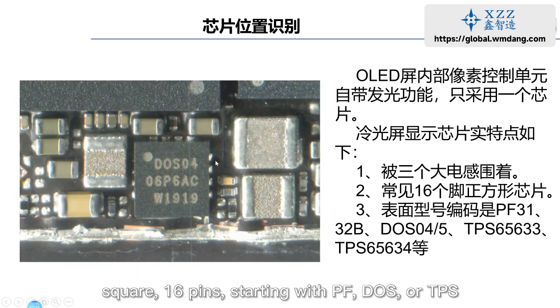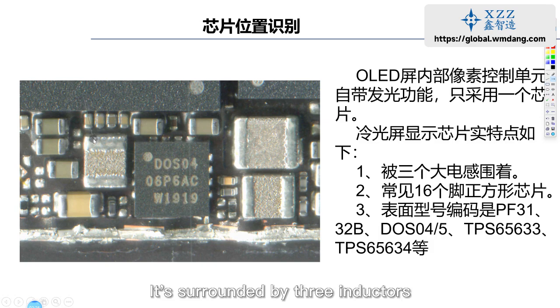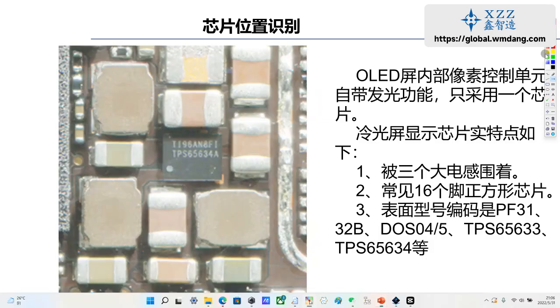This is its appearance feature: surrounded by three inductors, square, 16 pins, starting with PF, DOS, or TPS. This is also a display power supply chip. Its number is DOS04. It's surrounded by three inductors. This is an OLED screen.